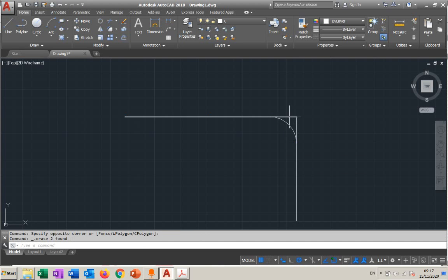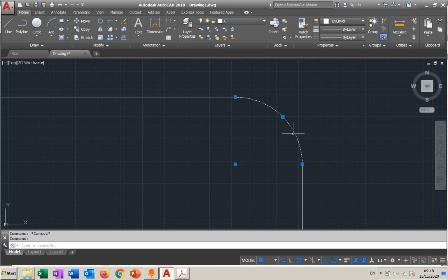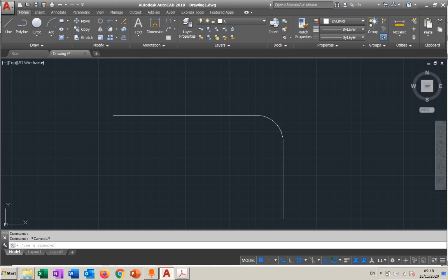Then we had to delete those parts, and this one you have to simply manage to come back to the beginning of the arc. Yes, you have to come back to the beginning of the arc. Why? Because it will be a round corner. Look, this is a part of the circle which is tangent to this line, tangent to this line, and has a radius. So all of these things I've done here.